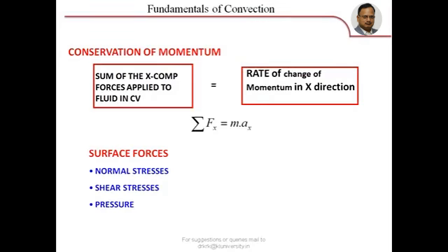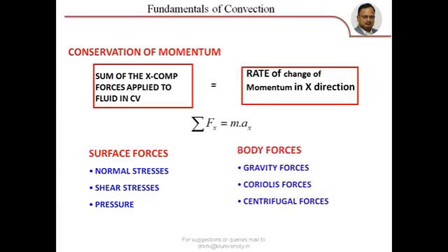So if you consider a fluid element in the boundary, it will be subjected to different forces. And what are all those forces to which it is subjected? Number one, surface forces, and number two, body forces. These surface forces are normal stresses, shear stresses, and pressure.